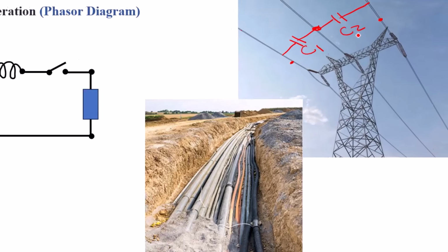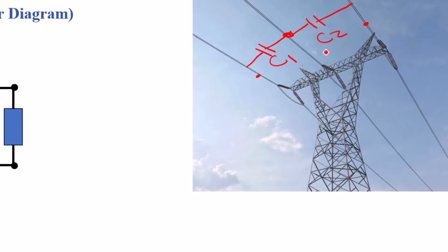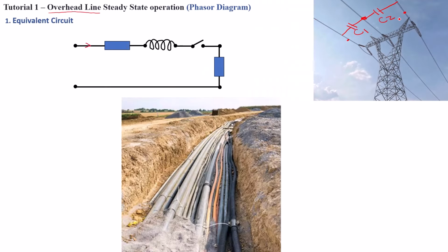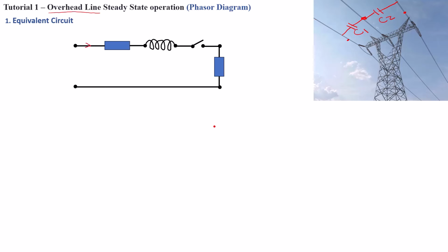As can be seen here on the normal overhead transmission line, the line spacing between the cables can go up to 1 meter of spacing. But this is not the case in the underground. The cables are going to be bundled together, very tightly close together, and in that situation the capacitance is going to be much higher. So you cannot do an analysis the same way we do for overhead transmission lines.